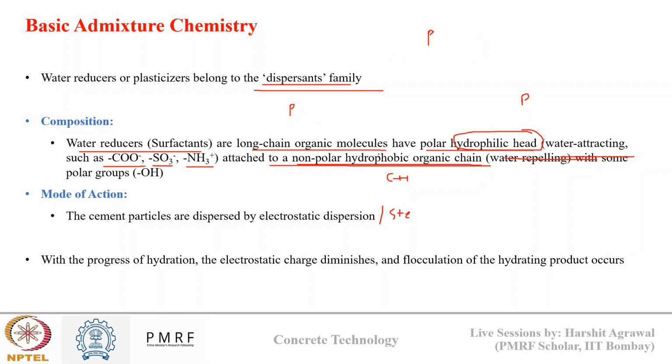And over time, as the water is consumed, the electrostatic dispersion that was occurring due to the plasticizer diminishes, and again the cement grains which are separated after hydration flocculate into final products and they densify the concrete.